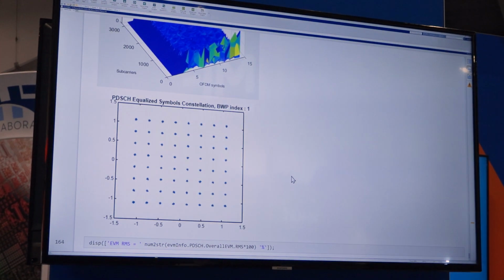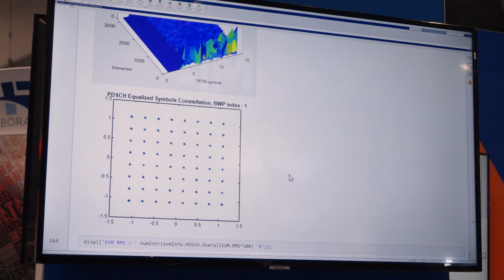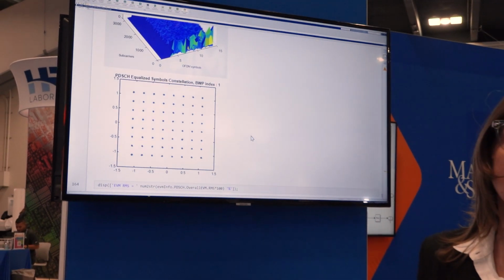Because our 5G reference receiver also includes an equalizer, and it equalizes all the dispersive effects introduced by the channel. In this case, dispersion is introduced by the transmitter, so you don't need to spend lots of time in making the transmitter perfectly flat, because effectively this behavior gets corrected in the digital baseband domain.